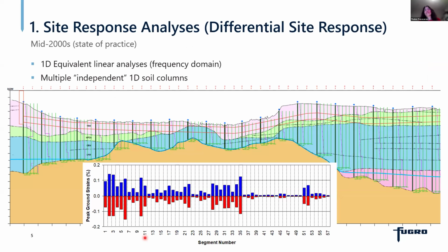Starting with site response analysis and differential site response. When we were defining the methodology at the time for assessing the differential site response along the tunnel, we concluded that although there were nonlinear tools available, for example, through software like DMOD or DESRA, nonlinear site response analysis was not routinely performed, and selecting such a tool as our baseline would probably have had a hard time during a review process. So at the time, we opted to perform one-dimensional equivalent linear analysis in the frequency domain, a tool that had been widely used and accepted in practice.